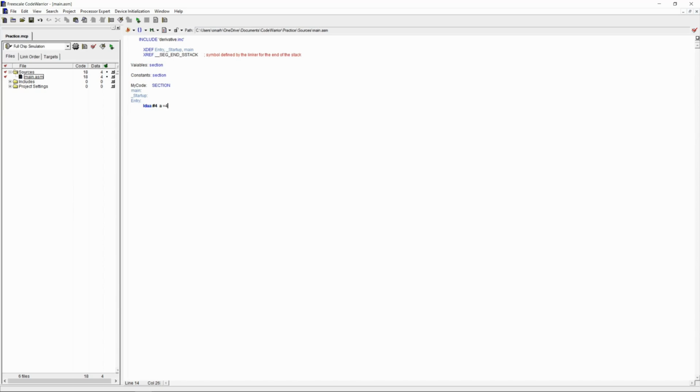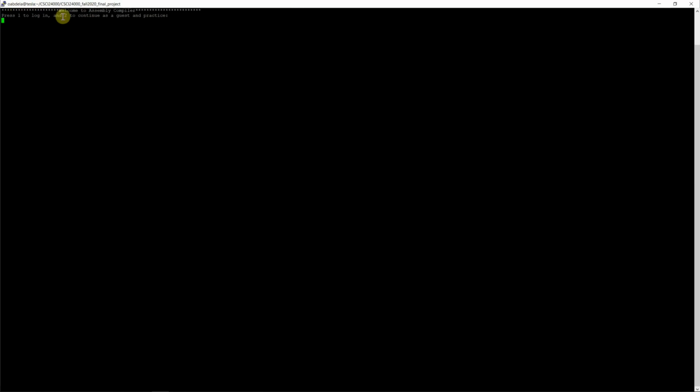And so the number that is right after the pound sign is being transferred or stored into accumulator A. Now I programmed this program a while ago, and it'll help us understand and see more easily what is going on every time we use immediate addressing mode. So let's write, for example, LDAB, and then immediate addressing mode starts with the pound sign, and then 2. Now we can see that in register B, or in accumulator B, the value 2 that we wrote is immediately being transferred into the accumulator.